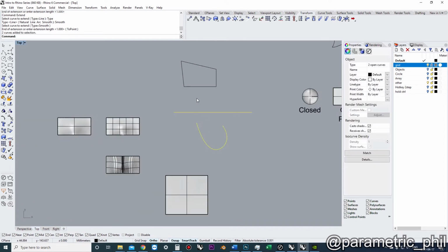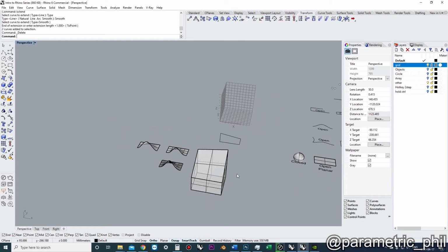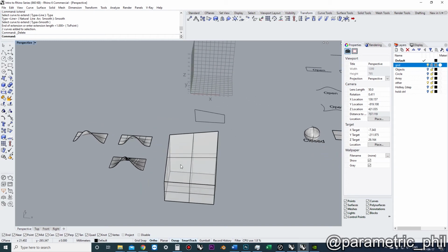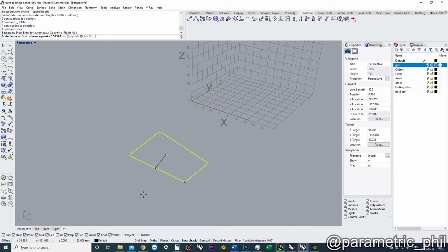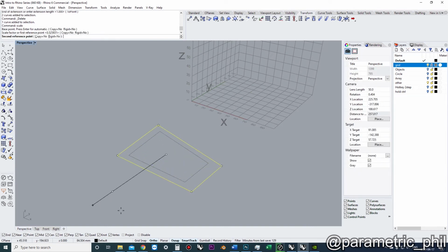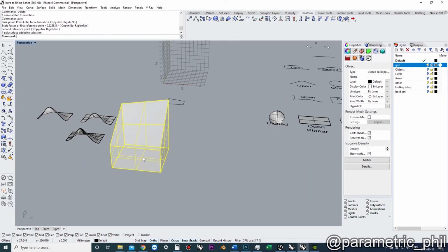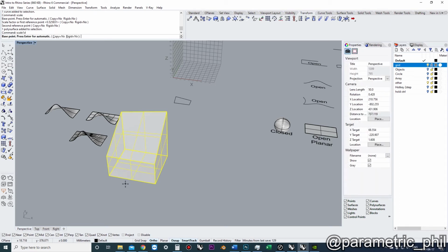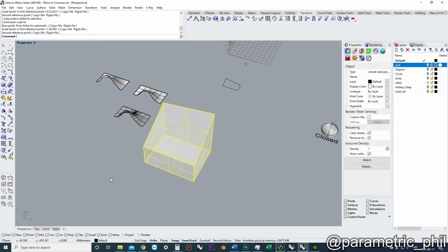Okay, here's another command that's really valuable for curves, surfaces, for any type of geometry. Scale 1D and scale 3D, I think, are going to be used a lot. So when it comes to scale 3D, I think that kind of makes sense. We can scale an object like this. But let's say I just want to change the dimension of this object in one dimension, then I can go to scale 1D, and then I can choose to change the direction of it like this.